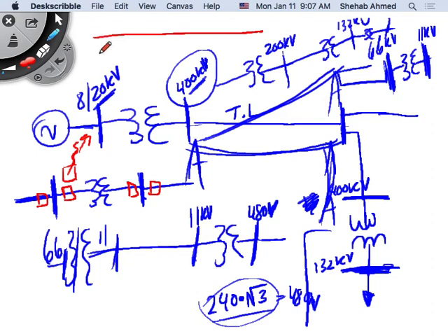One way to protect it is to measure current here, and measure current here. If there's a difference in current, what happens? That means that there's a problem somewhere in the middle. This is a cable, so the current has to be the same. There's a voltage drop across the cable, yes, but the current has to be the same. So if the current has any deviations from the beginning to the end, then this is an indication that there's a problem in the middle somewhere. Maybe it's a small leakage or capacitive current, or we'll talk more about that later as well.